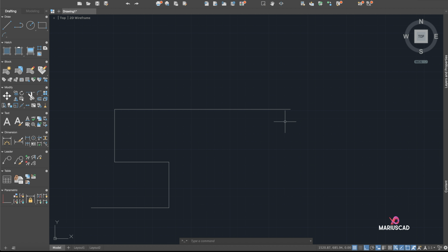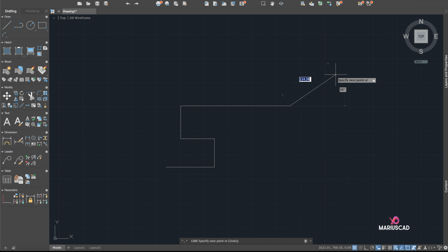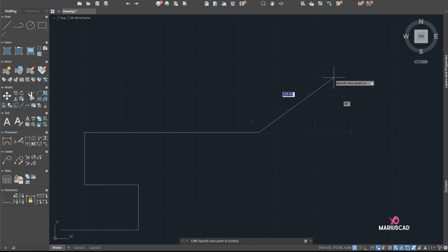But what I will do if I want to draw a line with another angle, to be not 90 like in this case, or 180. First of all, I will deactivate this ortho command, and then I have 3 options to do it. First option, line again, go here from this point, always find this green rectangle, always. Okay, and now I will go here. Okay, but I want an angle, let's say, of 30 degrees, but to be exact, not like 31 or 29, no, 30.